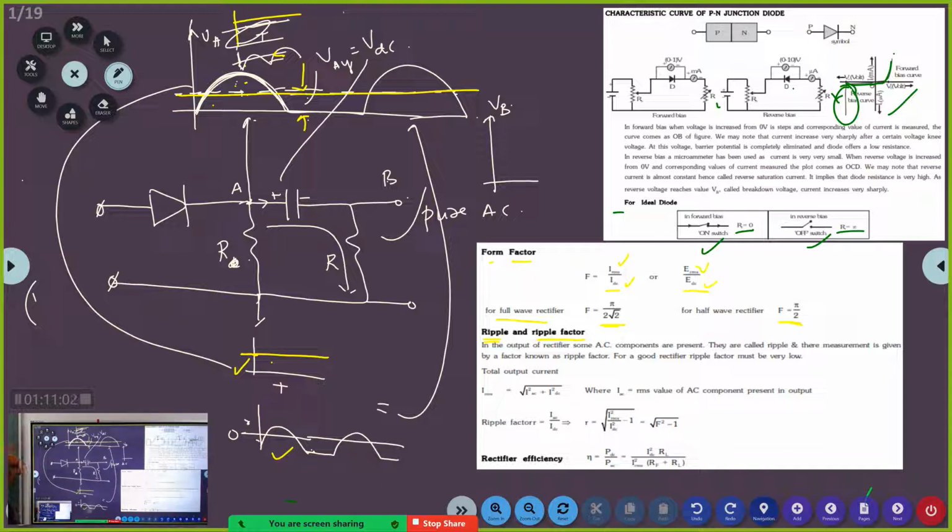The resultant waveform can explain. You try to correlate now. See, if I pass this signal through a capacitor, the capacitor will block the DC part and leave the AC part. So at this output, if you keep the oscilloscope, it will show like this. Correct? So to this waveform, if you add DC, what happens? The waveform shifts upward. This value is DC. Got it?